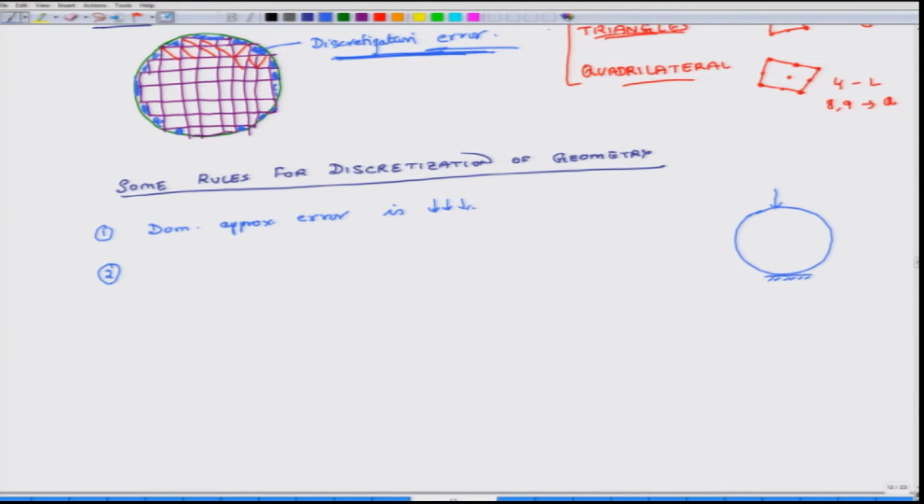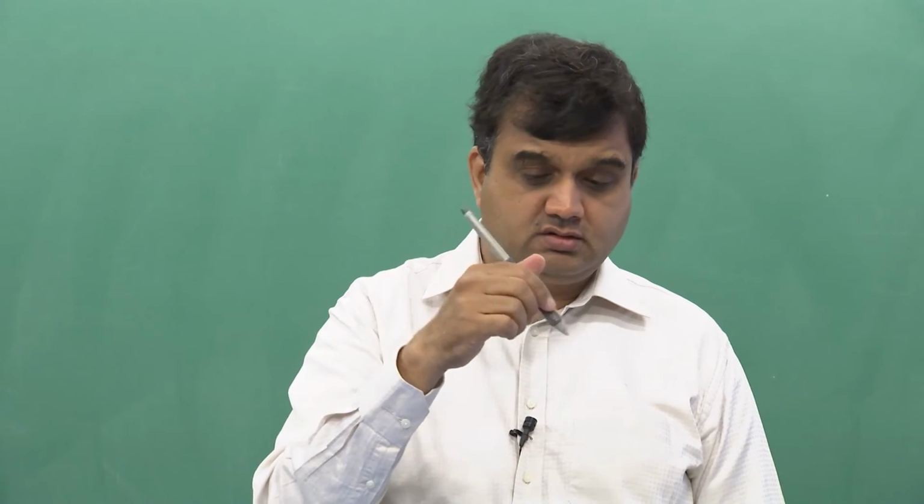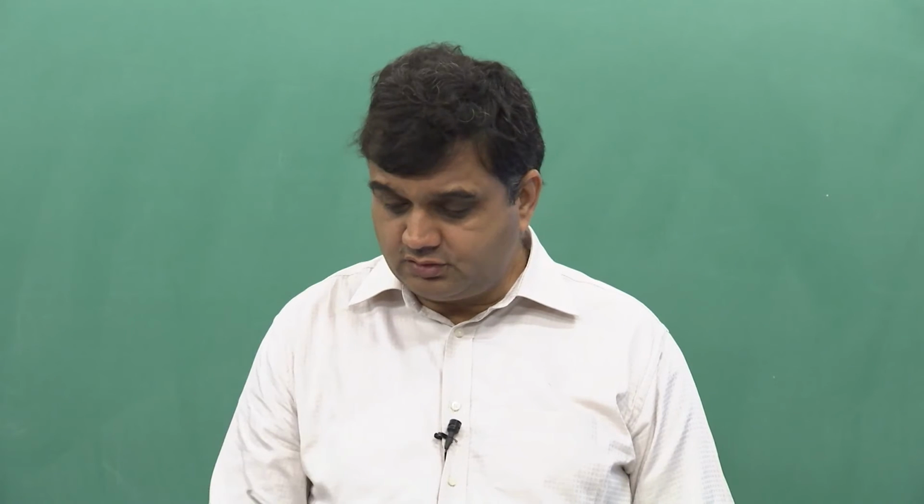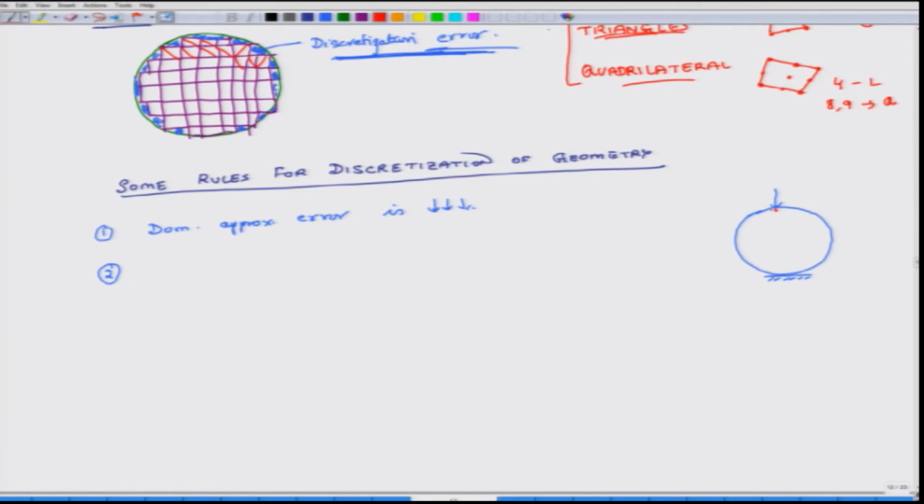Theoretically, if it is a point force, the stress here will be what? If I am applying a point force on a surface, what is theoretically the stress at that point? It will be infinite, because at that point there will be finite force divided by 0 area, infinite stress. So, what that means is that stresses will be extremely large here.